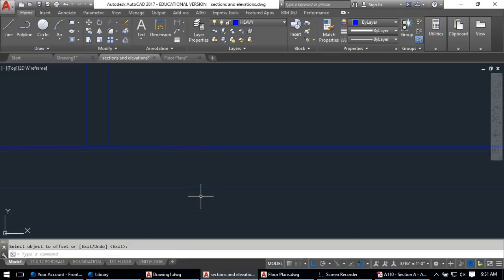And it does look like there's another. Is that drywall being shown there? The section is sort of unclear. There's definitely a double line there, it looks like to me, against the foundation wall. Let's see if I can see a note here. Yeah, there's not one specifically for the ceiling, but there definitely is for the side wall. So if there's one on the side wall, I'm going to assume it's on the ceiling too. So we'll offset another 0.5 inches for the material of that.